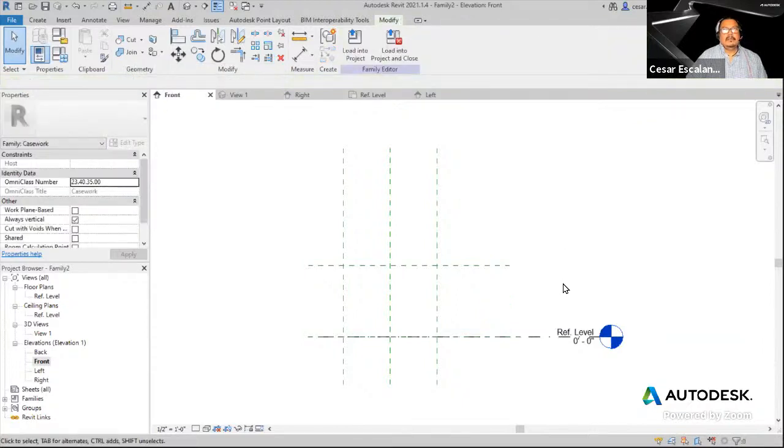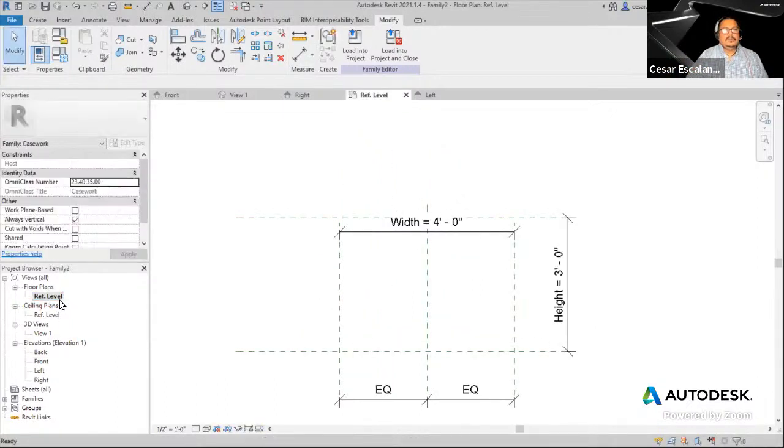Because this type of template is good if you're creating, like, a solid piece of equipment, but we're going to use the template just to create a door. The thickness of the door is going to be 1 inch, and that thickness is not going to be parametric. So remove it, so that I can also schedule the sizes appropriately.